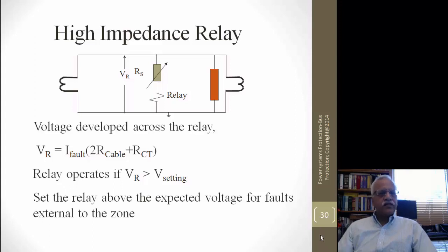So you can delay the operation of the relay to allow the CT to go into saturation and come out of saturation. The problem here is that if there is an internal fault, this relay will take the same amount of time. If the relay takes a lot of time to operate, that means you are delaying clearing a high fault current, which is normally seen at buses. So this could not be a great idea, but it has been used by several utilities by connecting a simple inverse time overcurrent relay. For an internal fault you see very high currents, so your operating time will be much less than for a fault outside, where it is only the differential current that is operating.